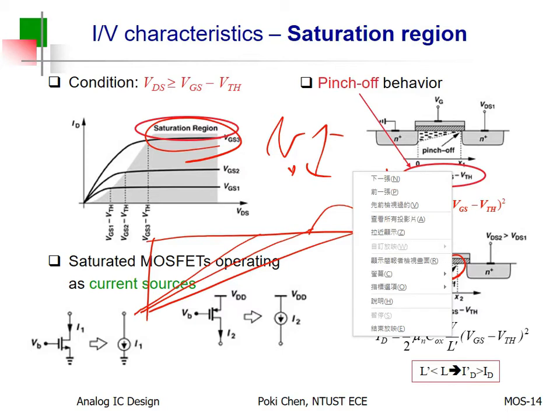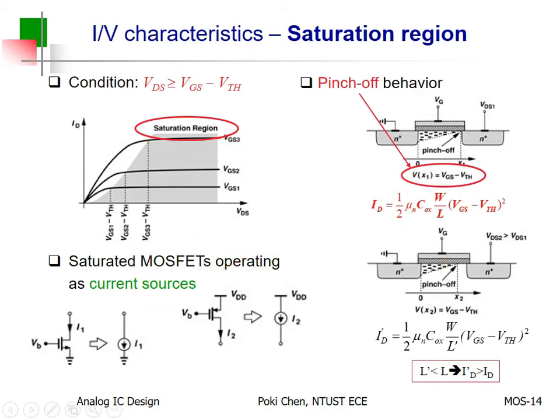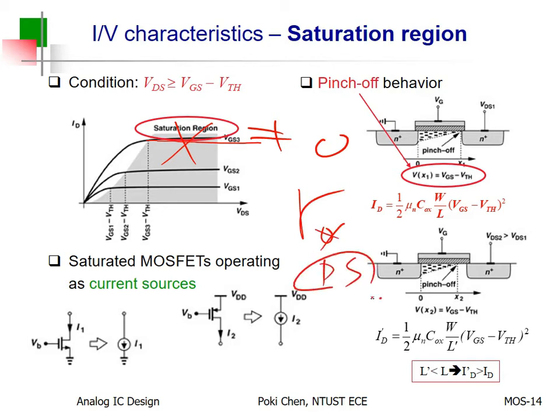Okay? Anyway, anyhow, the impact is the slope won't be zero. It has some kind of slope. That's it. So, the channel length modulation is what we hate because we hope it is flat here, and it means the output resistance between RDS. Okay? Output point is usually the drain. So, what is the output resistance? RDS. A source, again, is the reference point. So, RDS. Okay? That's it.